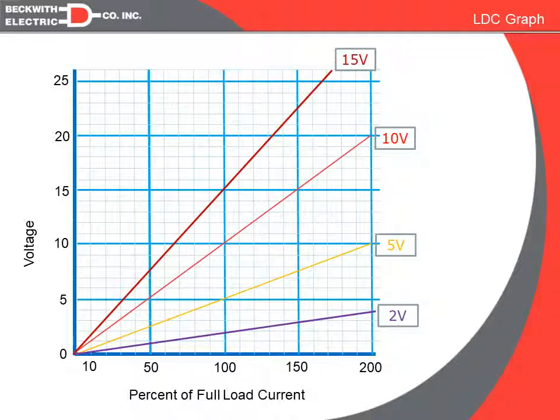So there is no cap on traditional line drop settings, R and X. We have to keep that in mind, because if we have more current than we anticipate, we could have an overvoltage situation.